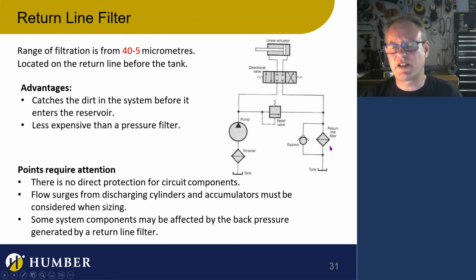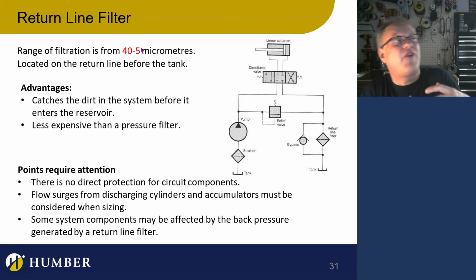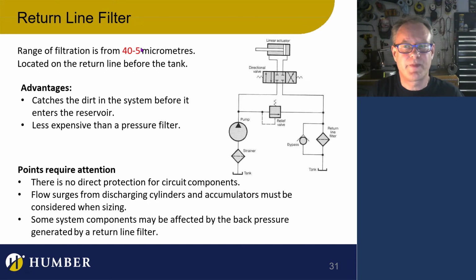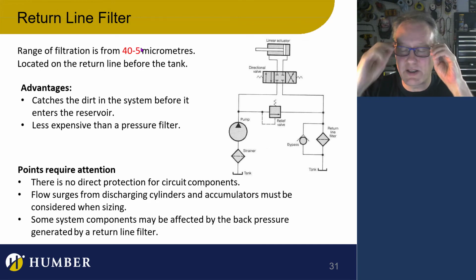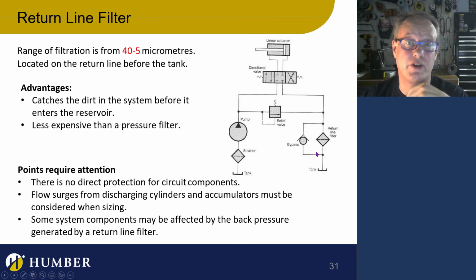But now let's take a look at this guy. If this guy does create some back pressure, which it will, because 5 microns is so small, it's going to slow the flow down, and it's going to fight the fluid. But you know what? It's still going to be under quite a bit of pressure. You might lose 100 psi or 50 psi across a filter. If it's really dirty, you're going to lose a couple hundred psi across it. But let's just say I'm going to lose 80 psi across this filter.